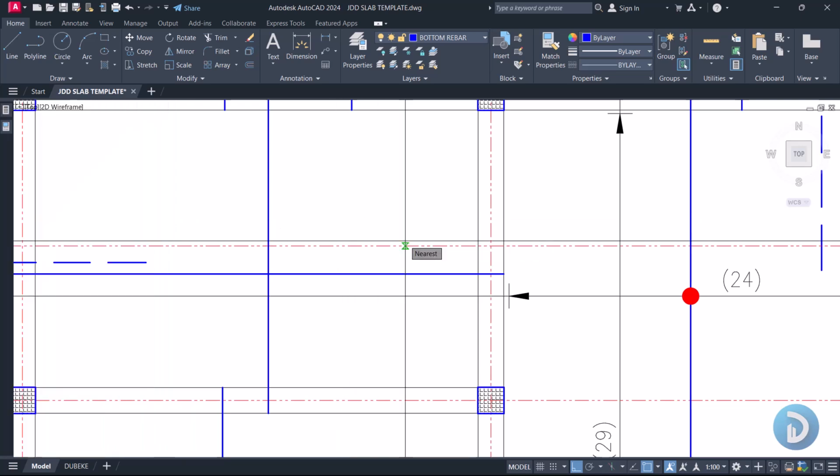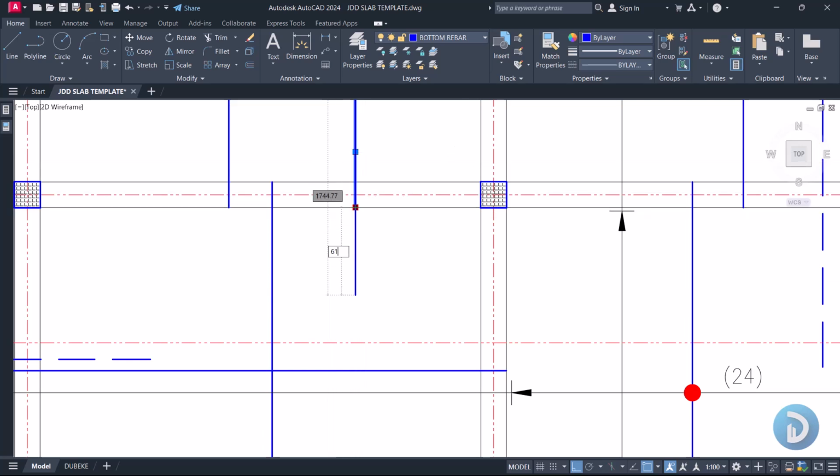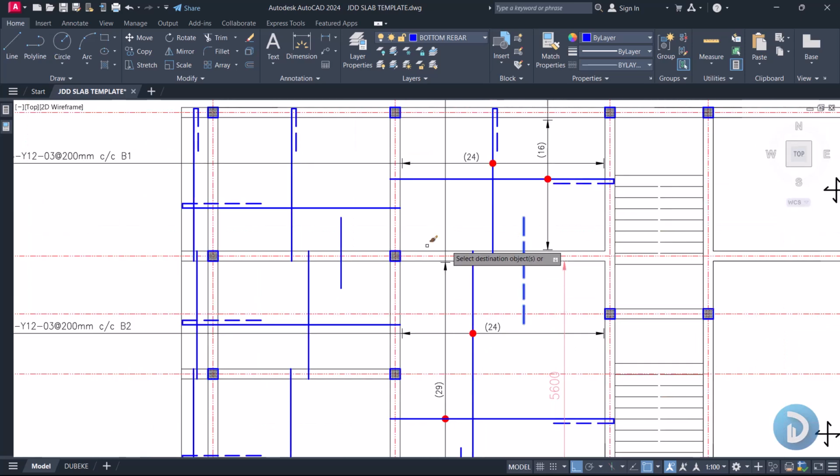And if you are detailing with software like CAD RC, it is advisable you always stick to your accurate dimensions, because this is what we use in the calculation of your general quantity, the quantity of your reinforcement required. Each and every one of these extended lengths is very important in estimating the quantity or the length of your reinforcement that is required. So we'll extend this at 610 from this point. Okay, then we can also match these properties to indicate this is our top bar.